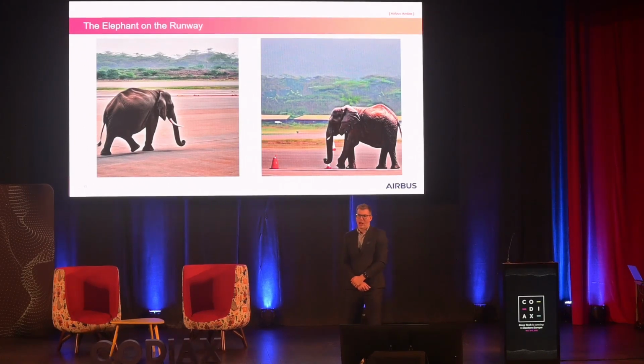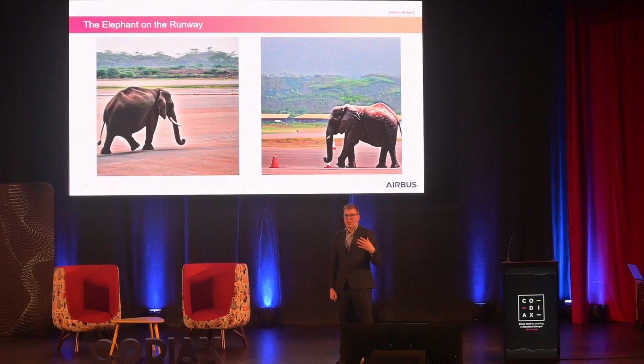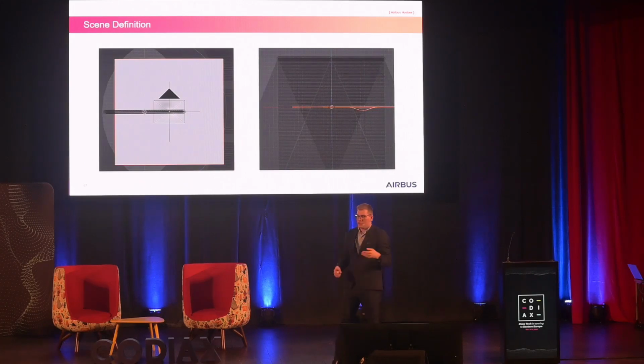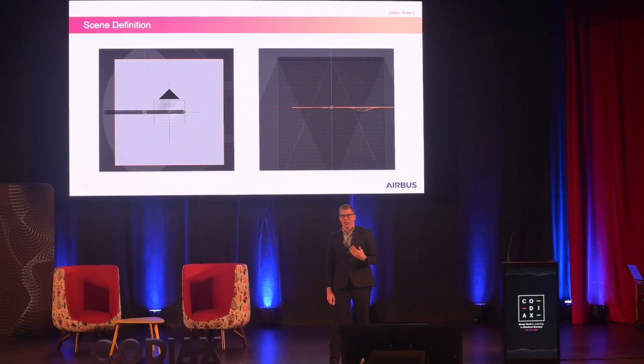In terms of how we would build a model or solve a problem, a general comment: this is something we haven't done yet, but we have ideas around monocular depth. When we generate the synthetic image, we have access not only to the RGB data coming out of the renderer and the location of the dent, but also to the range map, so how far away the aircraft surface is, and the geometry of the dent. So if we had the right model, and obviously models already exist for self-driving monocular depth prediction, we could use this as a training data set to train the model, even though in practice there's probably no real data set for dent detection.